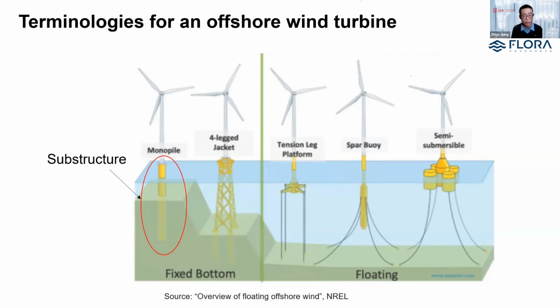Because of this unique feature, it's difficult to find harbors with very deep water depths, such that we can tow the entire spar platform in an upright position as it is. Usually we need to tow it in a horizontal position, then upend it at the designated offshore wind farm. There have been a lot of innovations in installation techniques for spar floating wind turbines. During my postdoc, I also spent a lot of effort looking at installation methods for spar foundations.